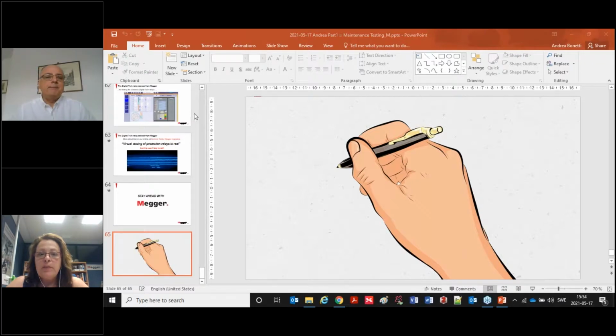All right. Okay. The question is, what is the frequency of maintenance testing of numerical relays for non-IEC 61850 substations? I cannot answer this question because it depends on the owner of the system. You have a digital relay, and maybe we can say, yes, the digital relay, no matter if it is 61850 or not, you can test it every 2 years because the digital relay has supervision, etc.